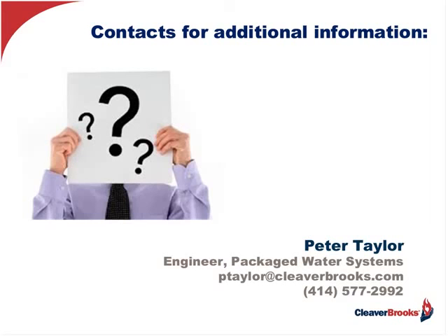Okay, next question. This one has a number of valves which are leaking in their system. They've replaced many and they still leak. Any suggestions? Oh, that's a very good question. Every valve has an ANSI shutoff classification with an associated leakage rating. That classification goes Class 2, Class 4, and Class 6. If you've got a Class 2 valve, it's going to have a certain leakage rate. They all leak to a certain extent. But the lower the class number, the more leakage is going to be incurred.